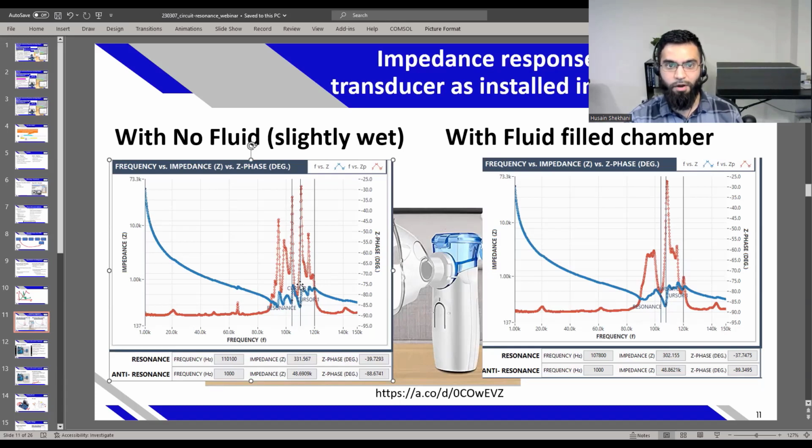That's why it confused me how it actually works, but it does, and there's still power that's generated. There are a whole bunch of reasons why this happens: you have a thin membrane which is resonating, you have symmetry issues, you have glue, and a lot of different things holding the edges. There are a lot of different problems with this, but it's still a functional device. It taught me about imperfection in transducers and dealing with that, the reality that not everything is a bolt-clamped transducer held at the nodal point. That's the reality I have to deal with. Not everybody has to deal with that if you don't work on various transducers.